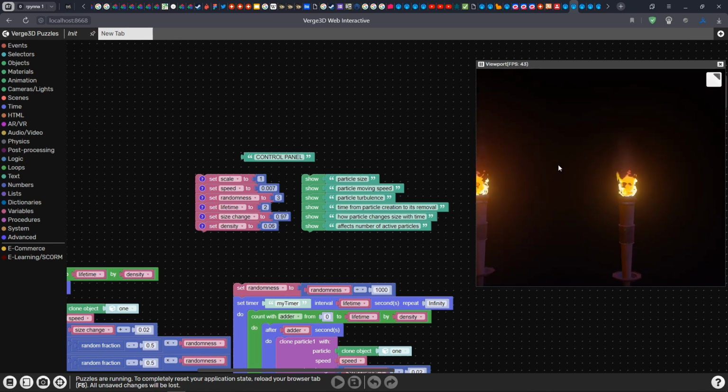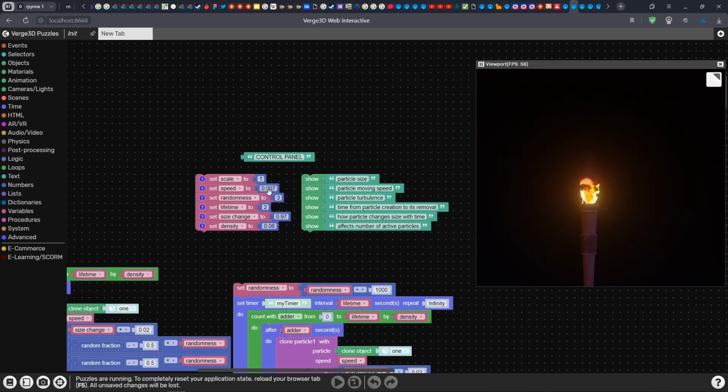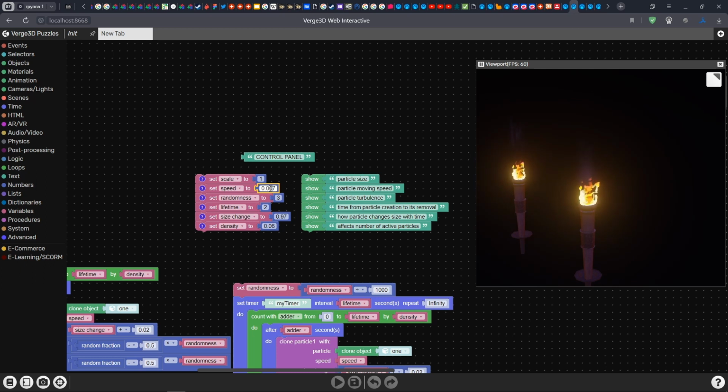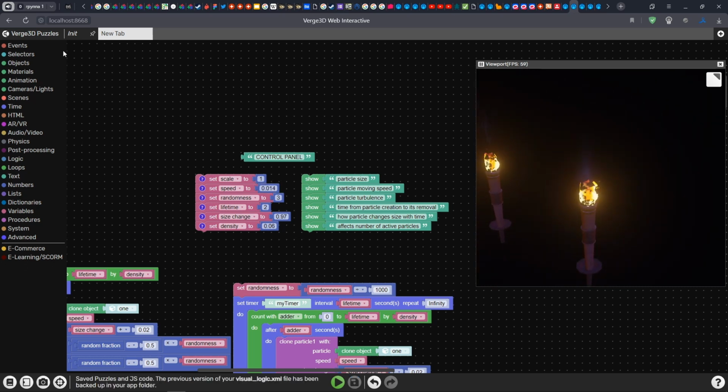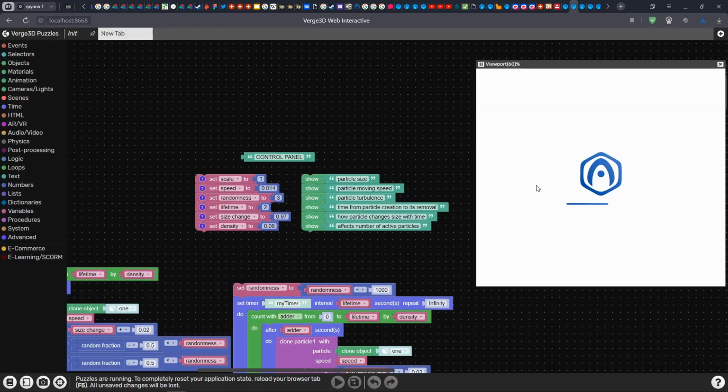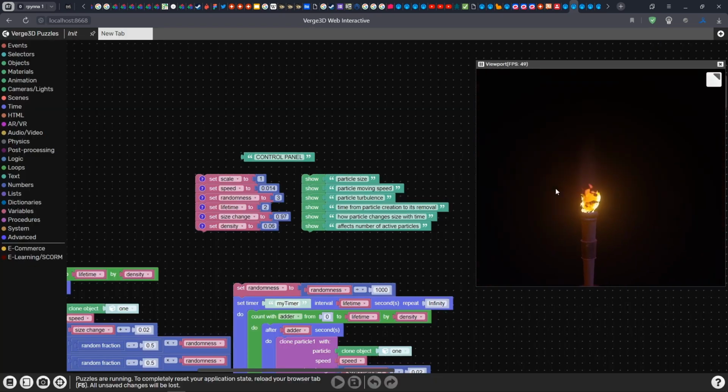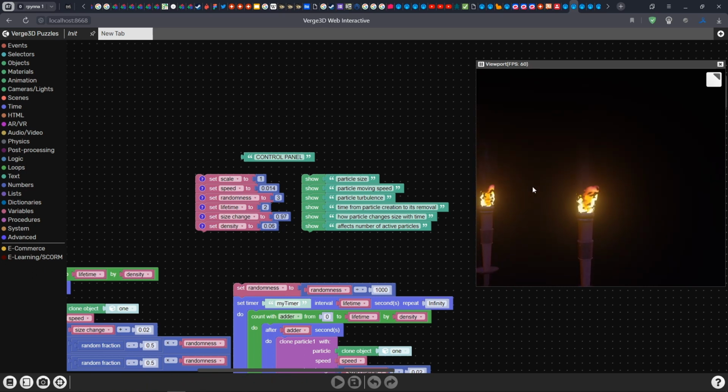The second option is speed, or particle moving speed. It is how fast the smoke is rising up. Let's keep in mind it is the global z-axis, so it rises globally up. This is a very delicate variable, so we are using very small numbers. Let's change it from 0.07 to 0.14, or twice as fast. Save and reload to see how they will move now. Alright, now the rising speed of the smoke is twice as fast.